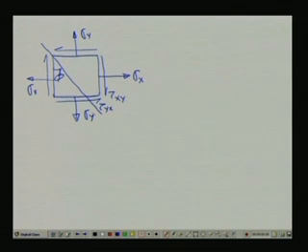What is meant is that this element is being acted upon by these loads. We know these loads, but if I make a plane cut at some angle, say here I have given it as phi, then what will be the stresses at these locations? There is a possibility that although here we can see sigma x of some magnitude, at some other plane the sigma x will change its magnitude, and those magnitudes could be larger than the sigma x we can see apparently for this plane.